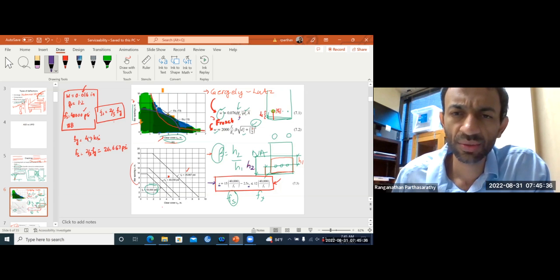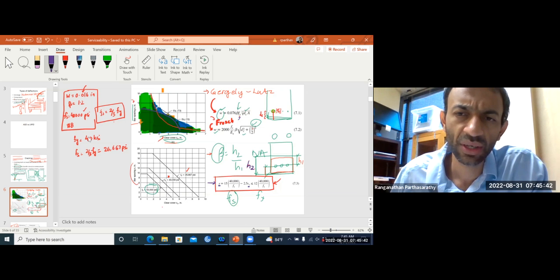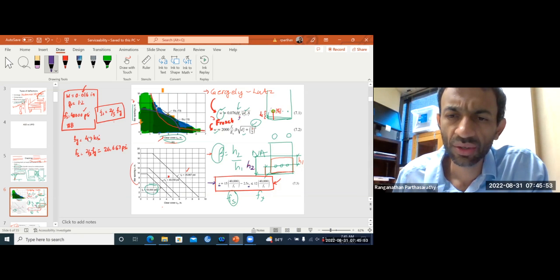Then dc is the distance from the tension face to the rebar centroids, and A is the area surrounding one rebar. You can calculate it based on the rebar spacing.